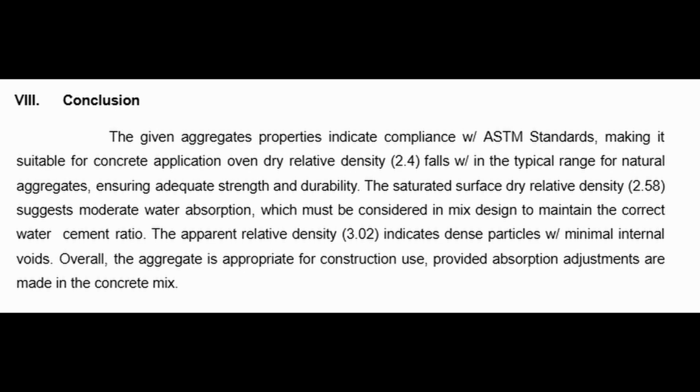Conclusion. The given aggregate's properties indicate compliance with ASTM standards, making it suitable for concrete application. Oven-dry relative density, which is 2.4, falls within the typical range for natural aggregates, ensuring adequate strength and durability. The saturated surface dry relative density, which is 2.58, suggests moderate water absorption, which must be considered in mix design to maintain the correct water-cement ratio.